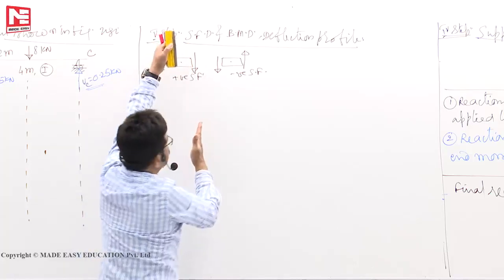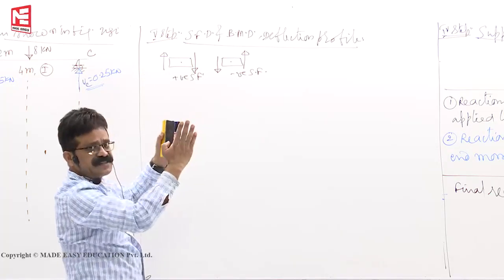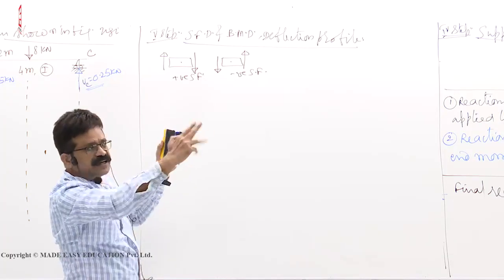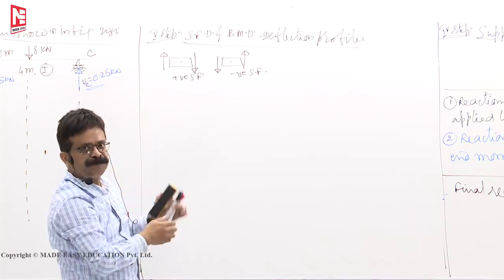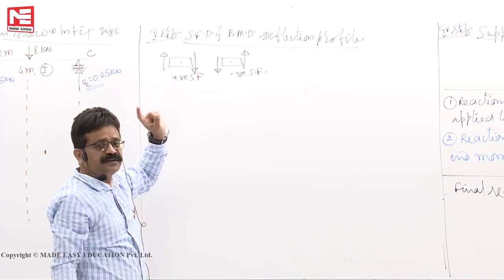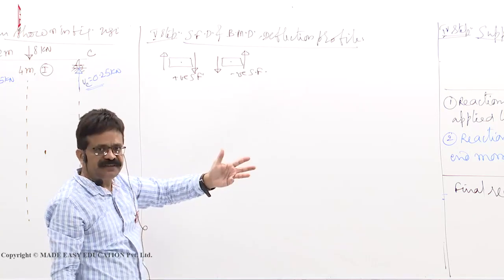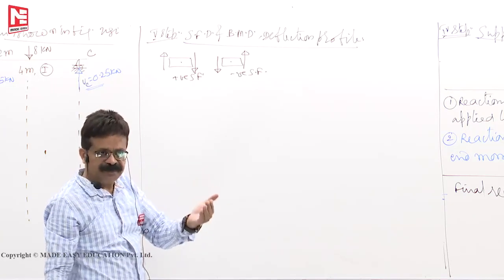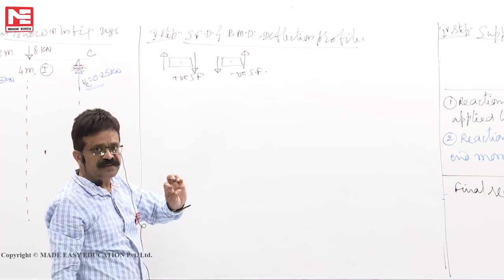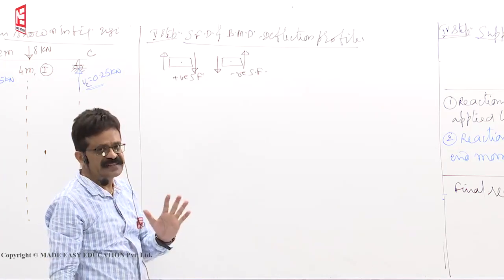When positive shear is there, the deformation I have shown you, the faces will remain parallel, only the longitudinal axis rotates, that's all. So that is the deflection profile. That means due to shear, deflections will be there. But like bending deflections, shear deflections we neglect, and deflections due to bending moment we will consider.